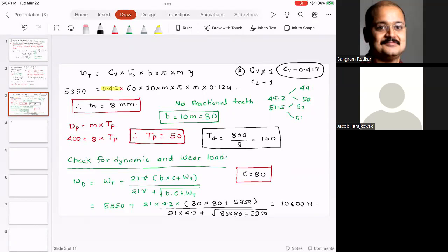Okay. As long as, so I just use that tooth error in action E, which is the cutter, has the error of 0.01. But if you say that I want to use the tooth error action as 0.02, that's totally fine. So what I'm trying to say is, as long as that value is within the reasonable range, it's okay.